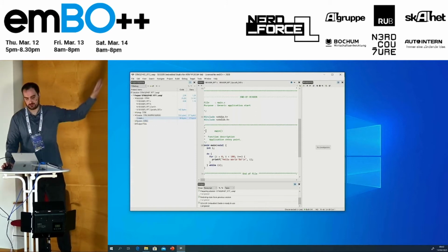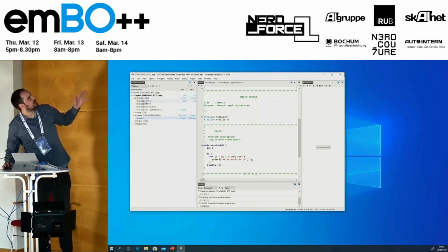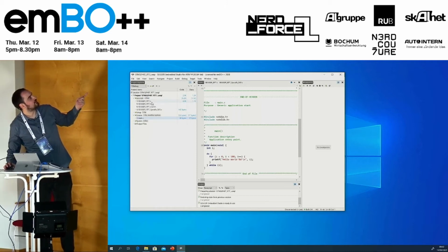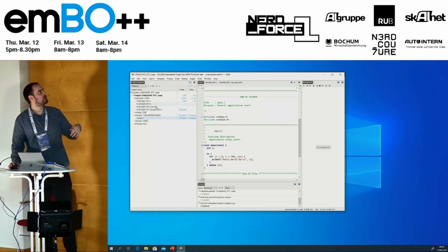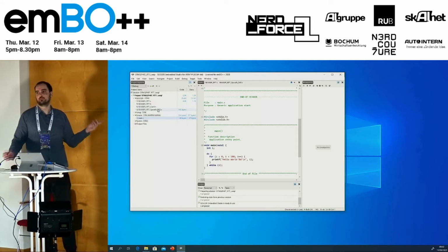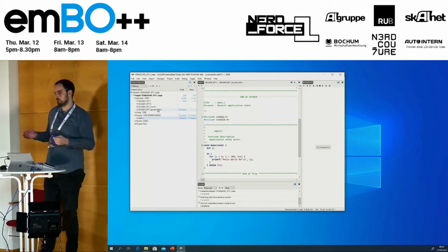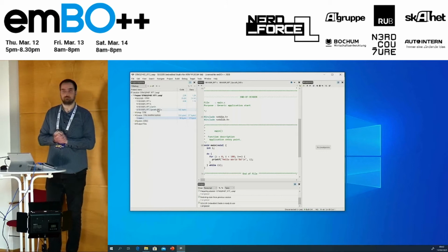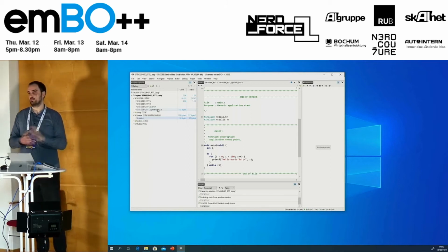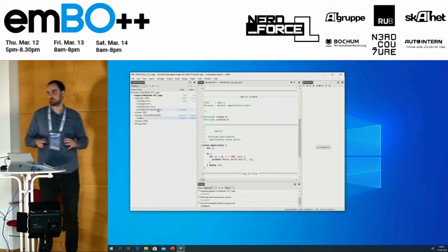I will just show this so you get an idea what you need to implement on your side. So it's just these 4 files. That's all I wanted to show. It's a C file, 2 header files for configurations of your up and down buffers, and we have also prepared for you syscalls files which replace the printf call for the standard implementation of most IDEs out there.